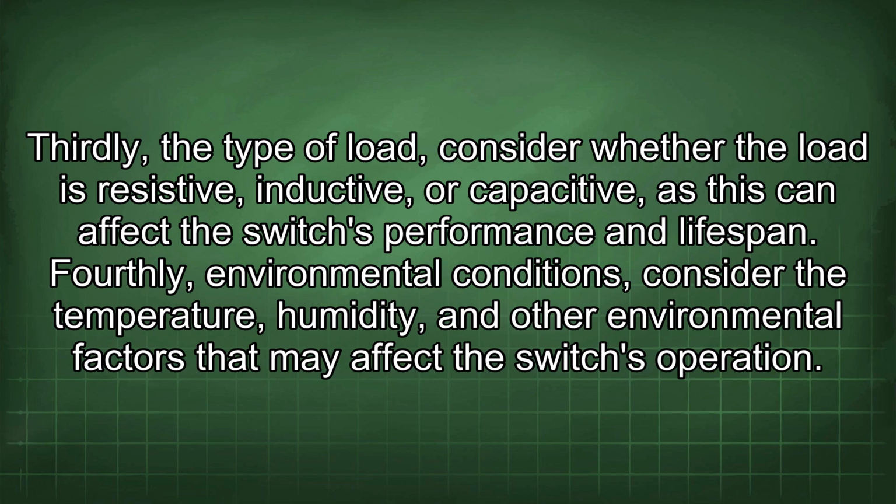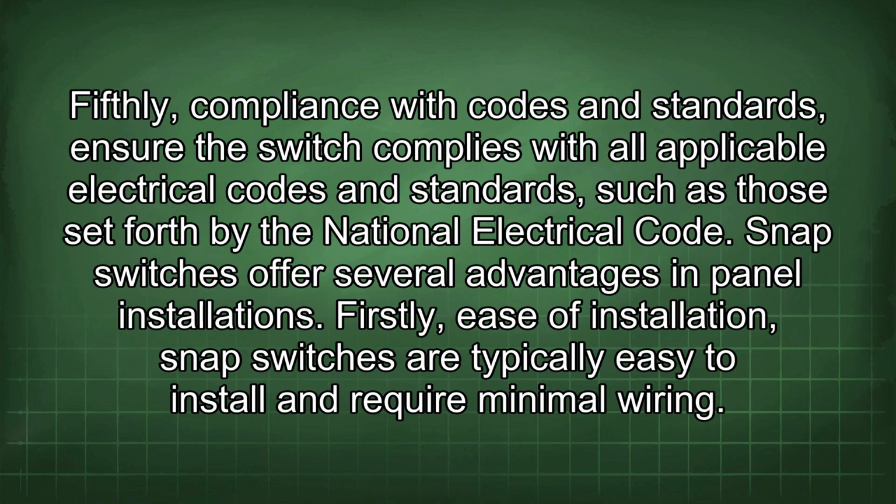Fourthly, environmental conditions. Consider the temperature, humidity, and other environmental factors that may affect the switch's operation. Fifthly, compliance with codes and standards. Ensure the switch complies with all applicable electrical codes and standards, such as those set forth by the National Electrical Code.